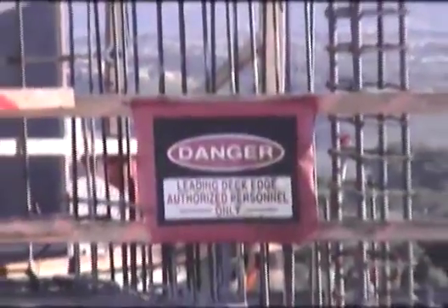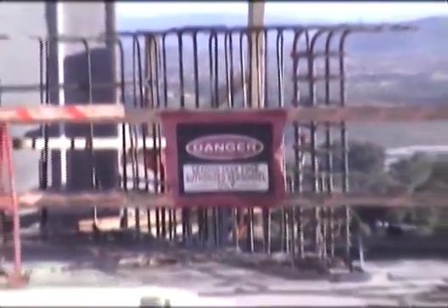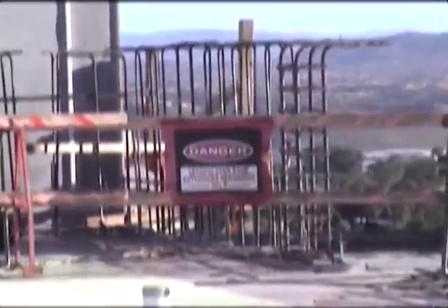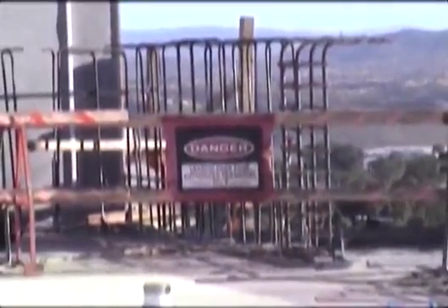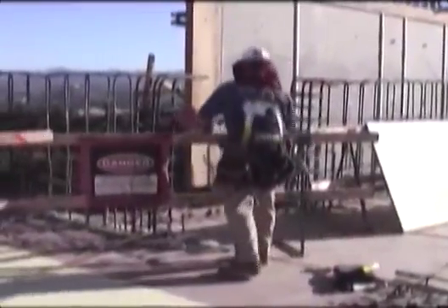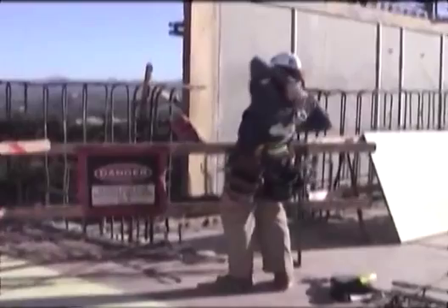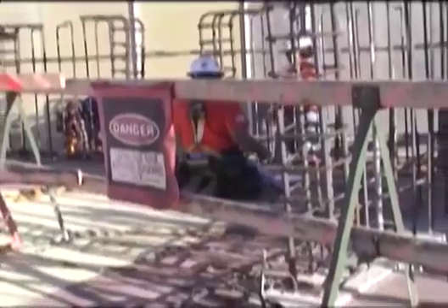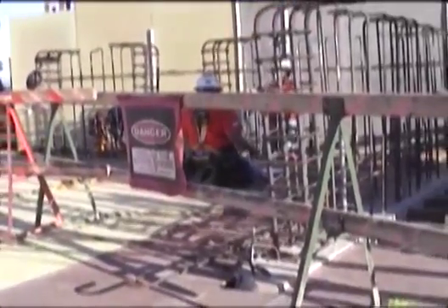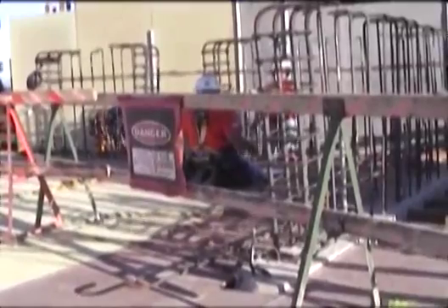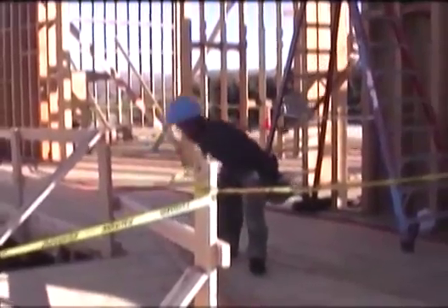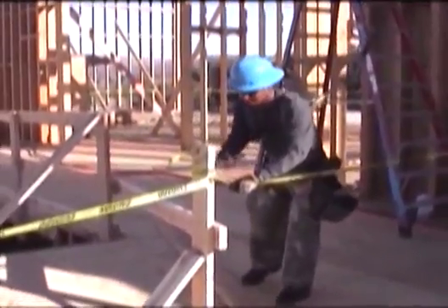A controlled access zone is a work area designated and clearly marked in which certain types of work may take place without conventional fall protection systems. Only qualified personnel involved in the operation are allowed to enter the zone. Controlled access zones must be defined by a control line or by any other means that restrict access. Control lines should consist of ropes, wires, tapes, or equivalent material, and should be flagged or clearly marked at not more than 6-foot intervals with high visibility material.